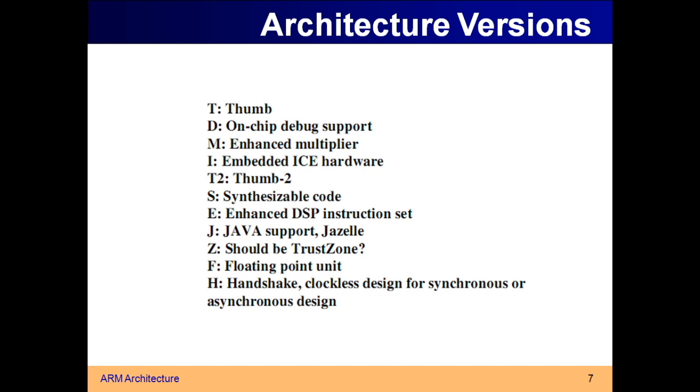In-circuit emulator: emulation means you are mimicking a hardware, that is known as emulation. Simulation means you are mimicking a hardware by using a software component. Emulation means you are mimicking a hardware or a microcontroller using another powerful hardware, that is known as an emulator. That means whatever operation is performed on the actual target hardware, you can see in real time using the in-circuit emulator hardware.